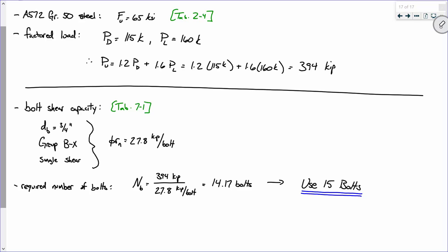No, in all seriousness, think about what's going on. Honestly, I don't even know that I would specify 14 bolts, because 14 bolts would have this big long row of 7 bolts, 7 times 2, right? It wouldn't collect that connection to a small grouped area. But 15, like you said, 3 times 5, it's a nice, small little region. Honestly, that's probably what I would do.